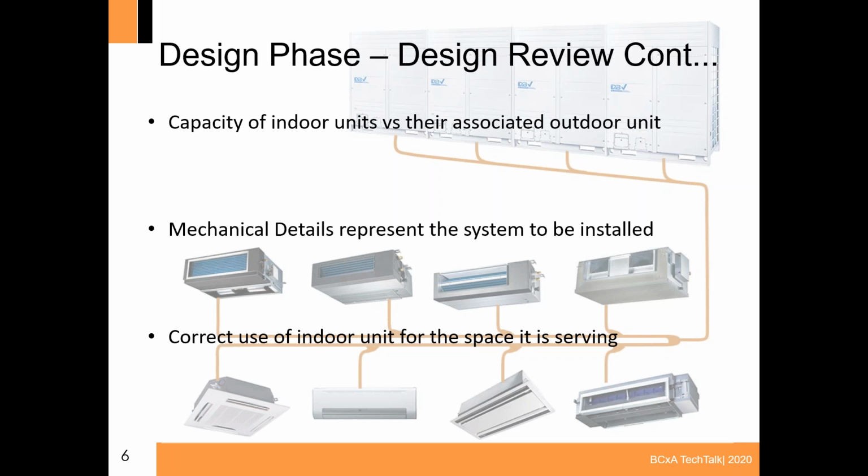And so all of a sudden, what was a storage room could now be an electrical room or some other sort of space. And what once had a ceiling grid no longer does. And the engineer could miss that. So it's worth looking at that. And all of a sudden you have this cassette sitting in this room with no ceiling grid. It's not technically the proper use for that, and it's kind of an eyesore. So if you can catch it, let the engineer know, hey, it may be better if you put in a wall mounted unit here. They'll probably be pretty grateful for that.